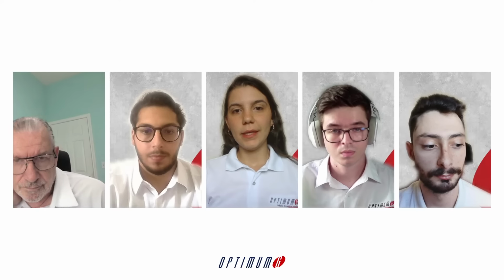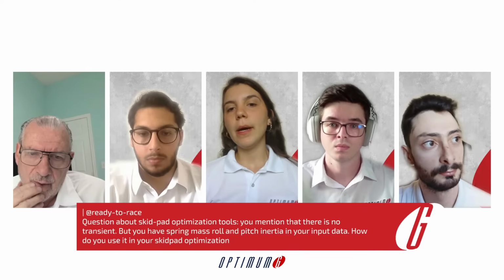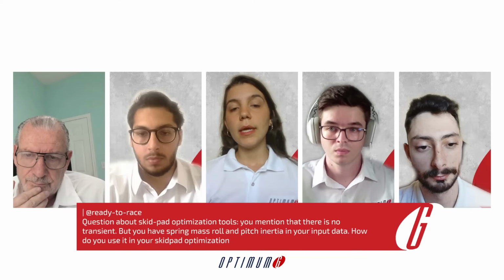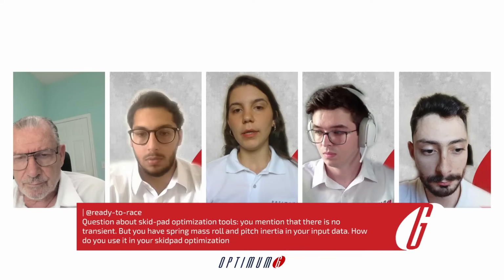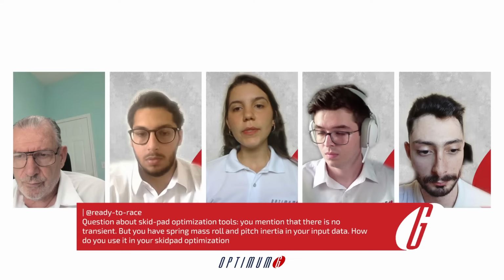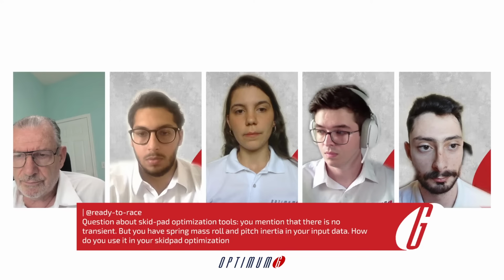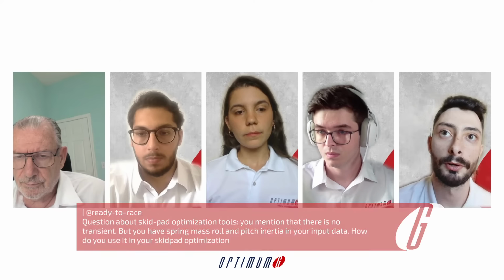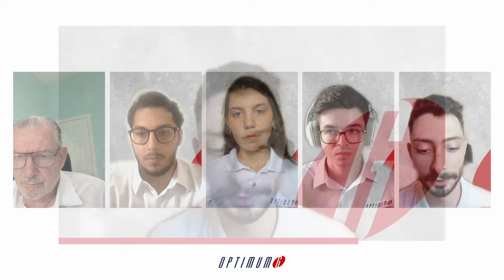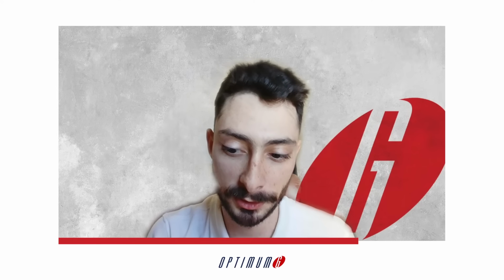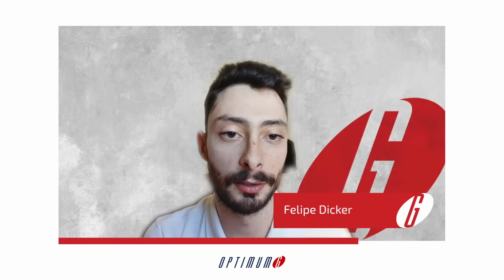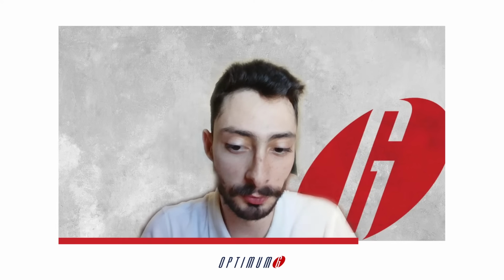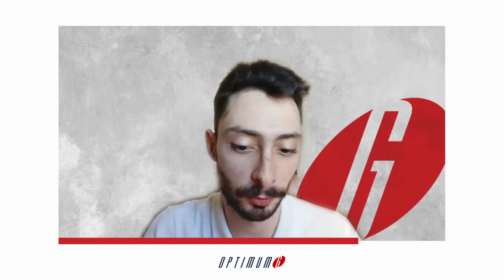Okay, thank you, Felipe. Our second question is coming from Ready to Race. The question is about skid pad optimization tools. You mentioned that there's no transient, but if you have a spring mass, roll and pitch inertia in your input data, how do you use it in your skid pad optimization? Yeah, so on this specific example of the skid pad optimization, these are just metrics that are calculated because we have an idea of how much the roll center moves at every different corner radius.